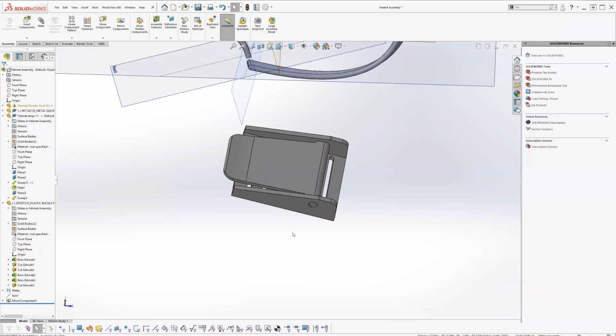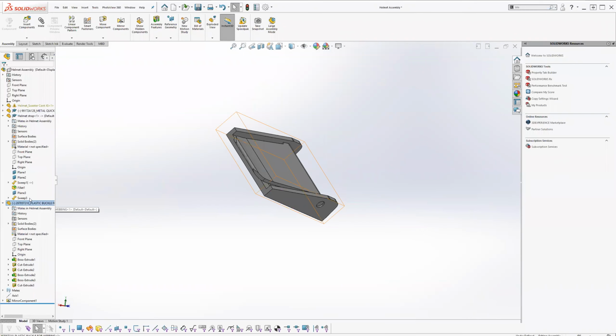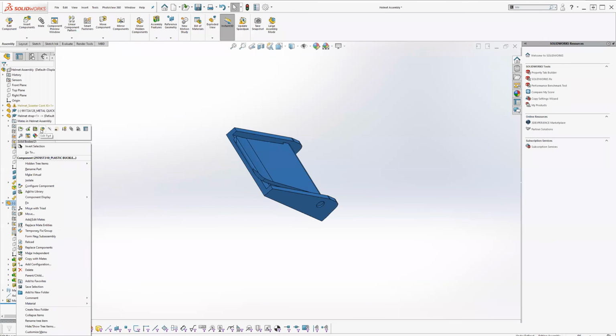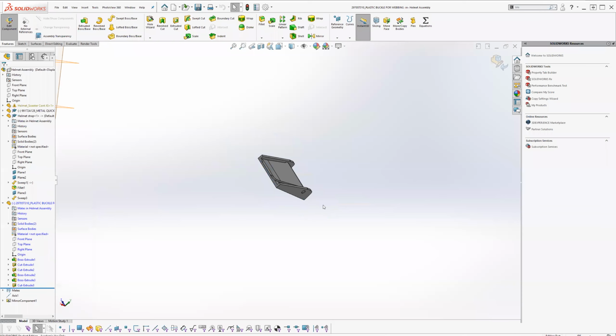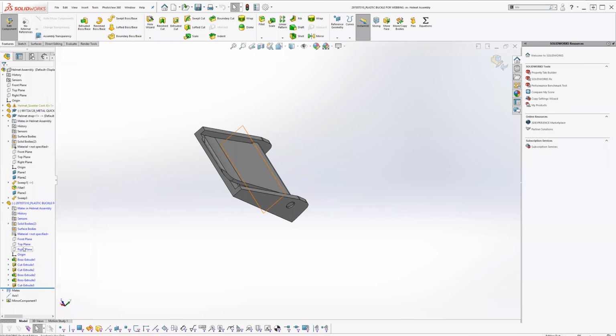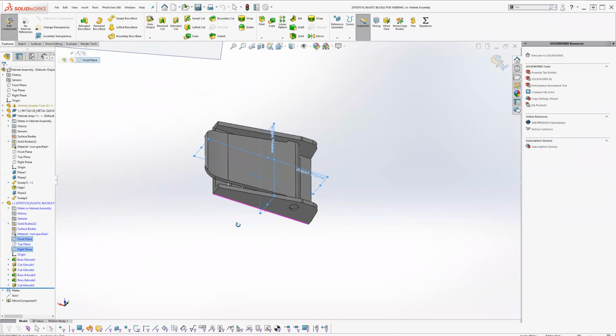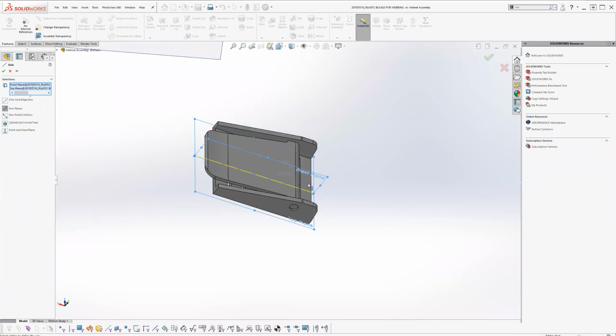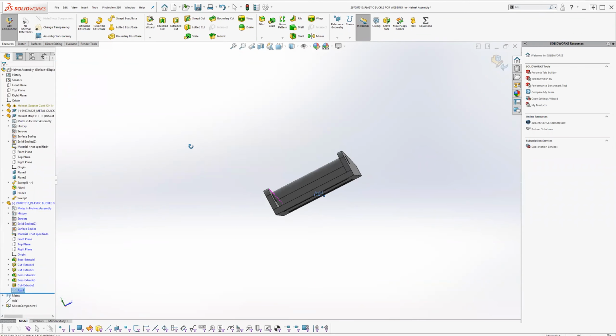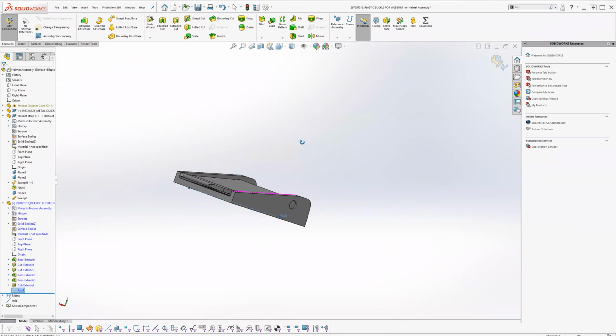So you can edit. I'm going to edit the part. Let's see, I'm going to make it out of two intersecting planes. Maybe these two intersecting planes. No, actually, I'm going to make the top one and the front. So from those two intersecting planes, I'm going to make an axis. So I have an axis going across there. Okay, so that's the middle of this piece.